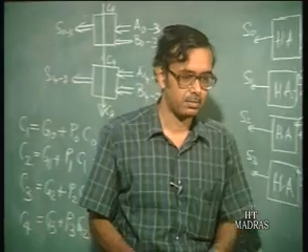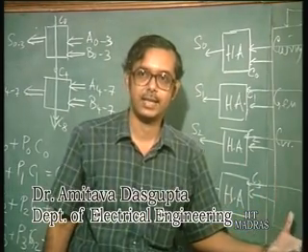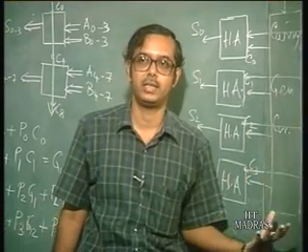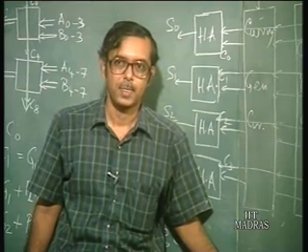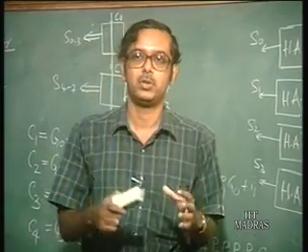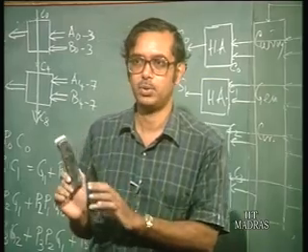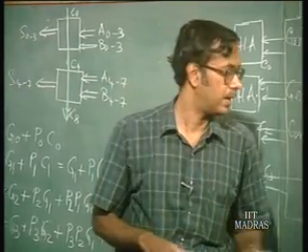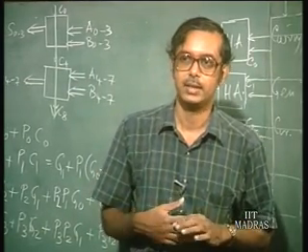Well, in the next class, we shall see how this is generated in a CMOS environment, and how you can improve the circuit or basically reduce the delay by using bipolar transistors to create a BiCMOS type carry propagation circuit. And we shall see that by using very few bipolar transistors, it is not that you are replacing a CMOS NAND gate by a BiCMOS NAND gate or a CMOS inverter by a BiCMOS inverter, but by the judicious introduction of bipolar transistors you can improve the delays. So, you have to see where you want to introduce the bipolar transistors and how it can improve the speed. We shall take that up in the next class.